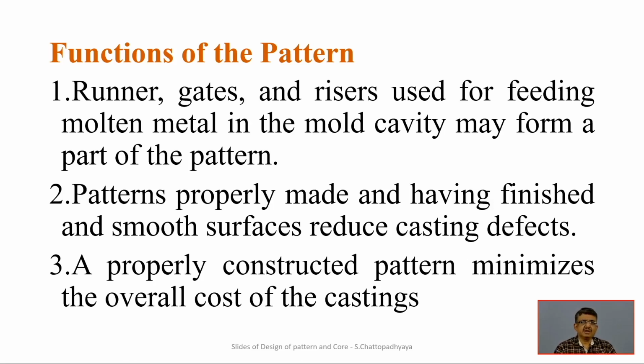A properly constructed pattern minimizes the overall cost of the casting. The reason is that you then have to do less machining, with fewer defects, fewer uncertainties and better surface finish, and all those things lead to a system where the quality of the castings and other things are much better. So one has to emphasize accuracies, surface finish, dimensional accuracies and other things at the appropriate level in order to get a good quality casting.